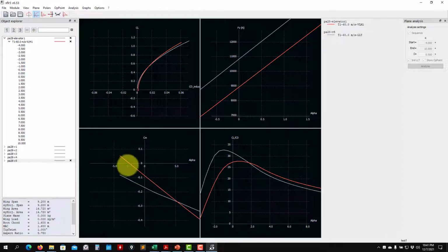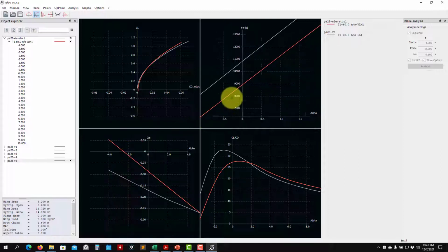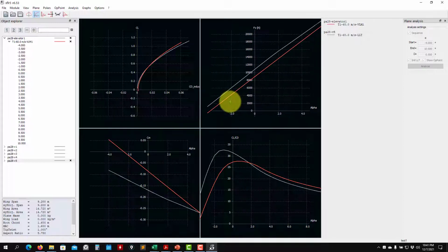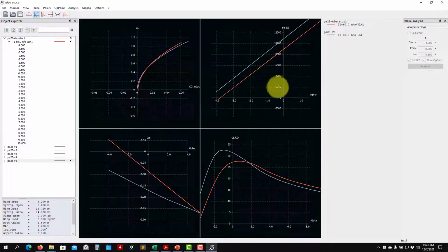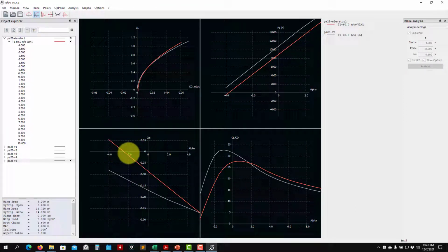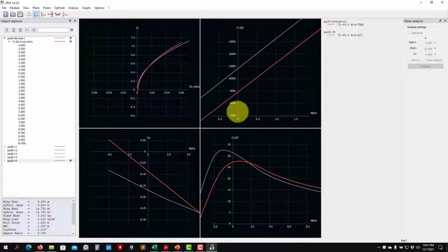See that now we are stabilizing the aircraft. See that now we are trimming. The trim condition of this airplane is something about 2.5, or let's say 3 degrees, -3. So here it is perfectly balanced. However, at -3, it's not generating enough lift. See that it is quite low. So what we need to do is reach that trim condition exactly when we want the cruise condition, that is, let's say 0 degrees. I want to reach this trim condition at 0 degrees.